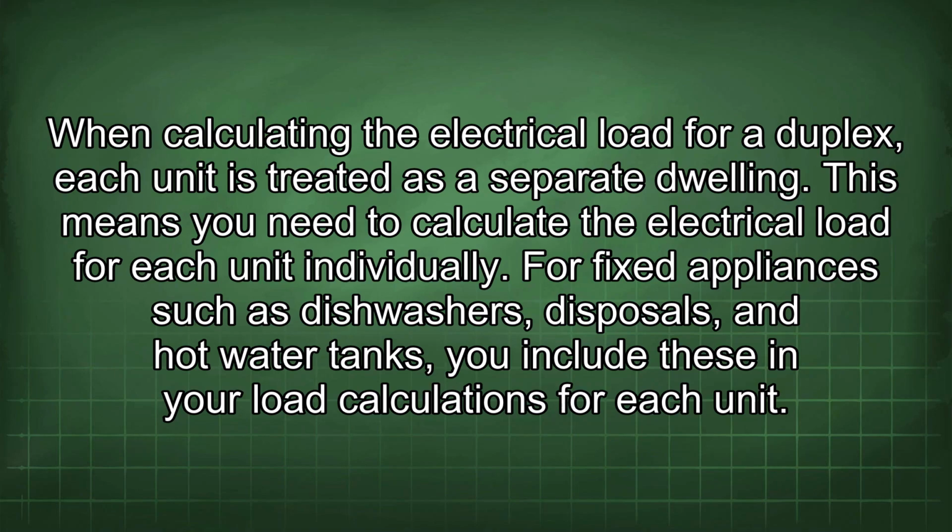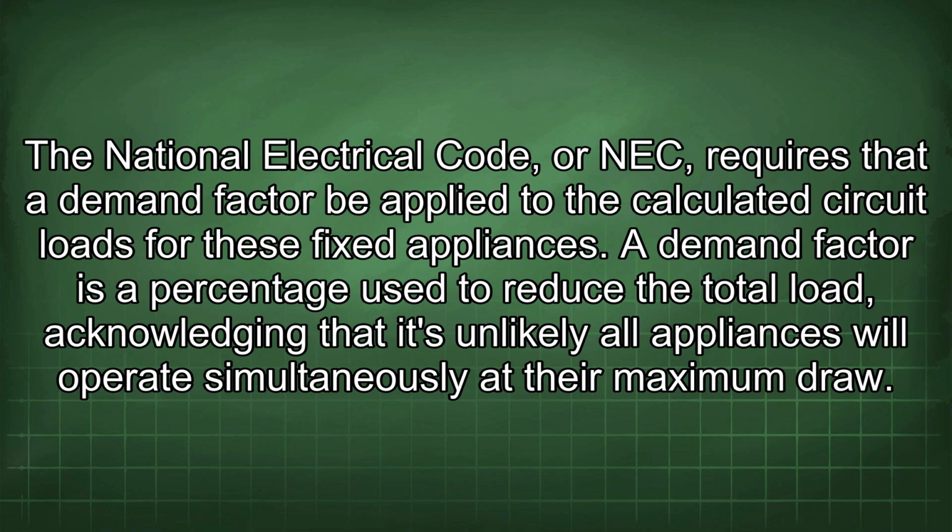When calculating the electrical load for a duplex, each unit is treated as a separate dwelling. This means you need to calculate the electrical load for each unit individually. For fixed appliances such as dishwashers, disposals, and hot water tanks, you include these in your load calculations for each unit. The National Electrical Code, or NEC, requires that a demand factor be applied to the calculated circuit loads for